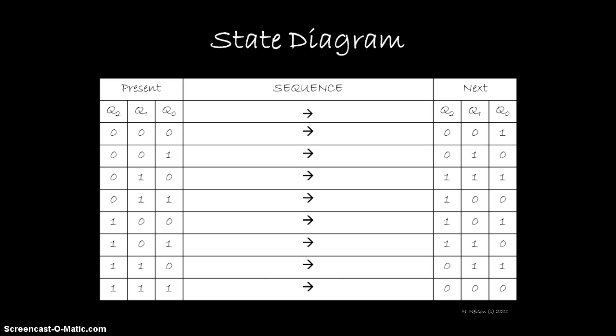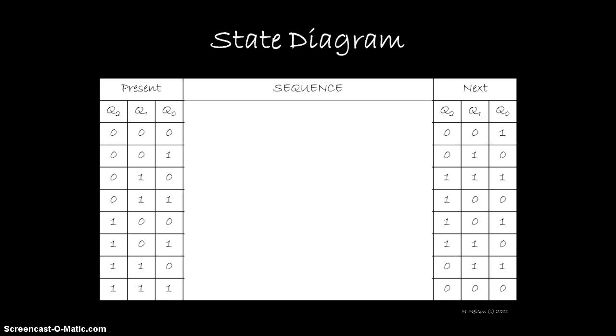The next row of the table identifies that any time the counter has a value of 1, its next count will be 2. From 2, it moves to 7. From 7, it goes back to 0. The corresponding state diagram shows these 4 transitions. A count of 0 moves to 1, then to 2, to 7, and back to 0. Each count is represented by a circular node, which is joined to the next node by an arrow. The remaining 4 rows must also be addressed.